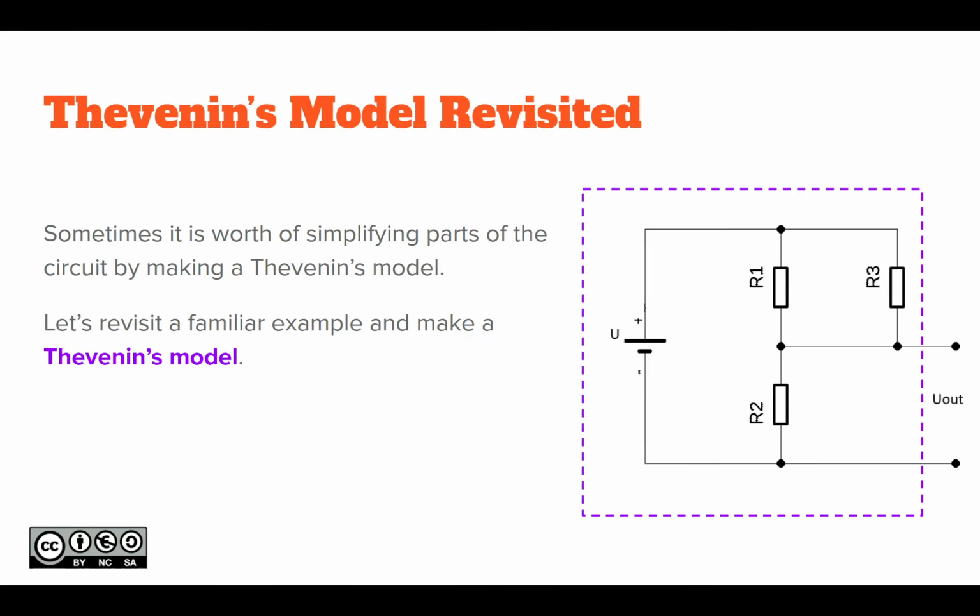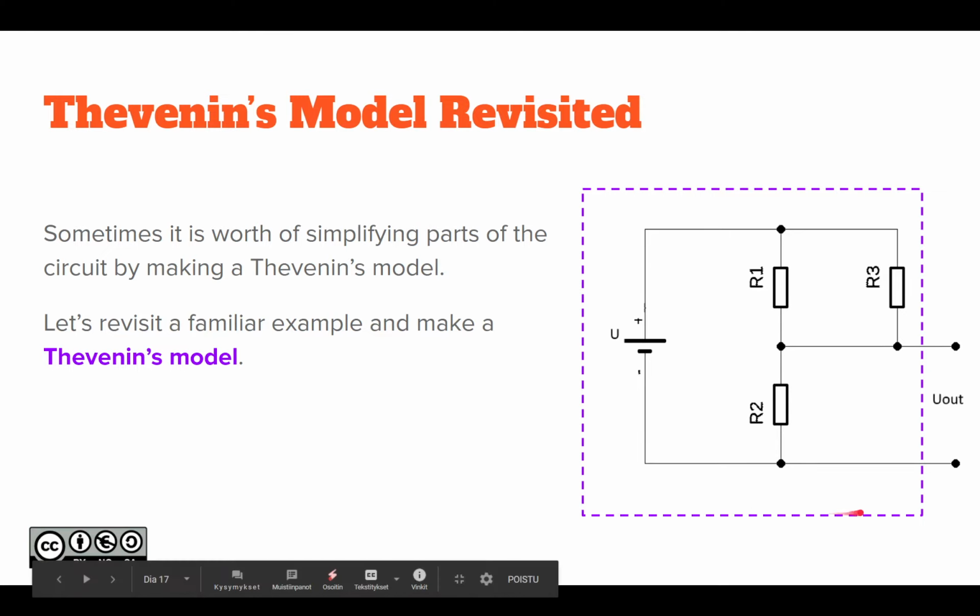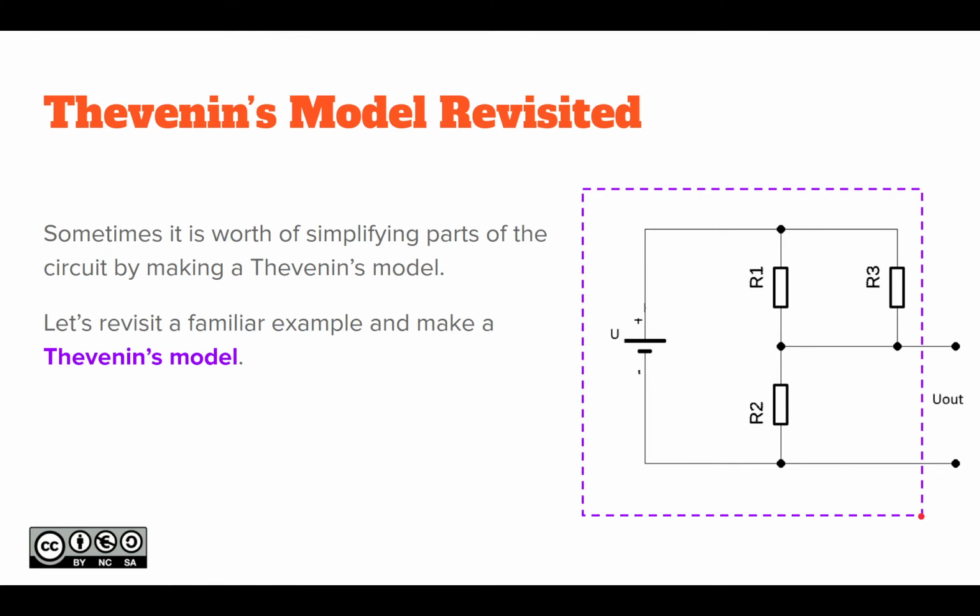So let's revisit the Thevenin's model. Sometimes it's worthwhile simplifying parts of the circuit by making the Thevenin's model. So practically that circuit diagram within this purple box, we can actually make a Thevenin's model for that one, and that one would also give you this U out at the same time.